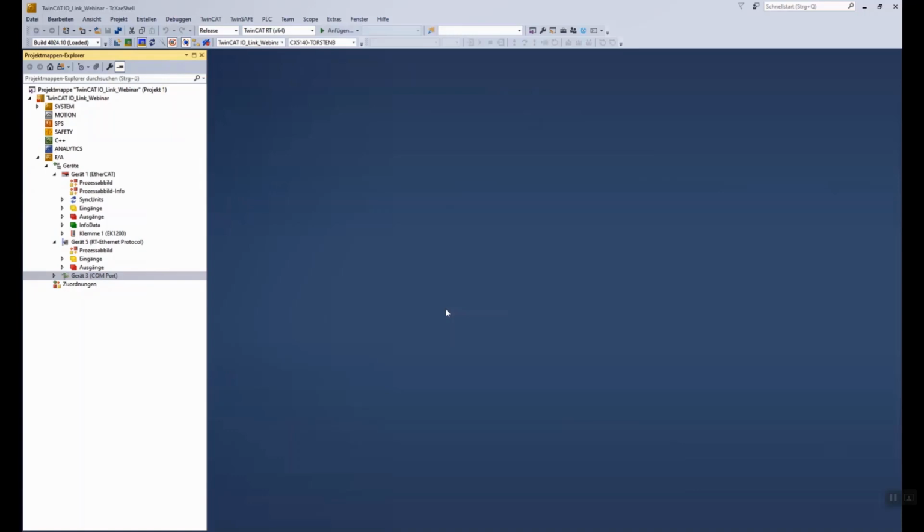IO-Link topology. And if an IODD file is not already on the local PC, then TwinCAT connects automatically to the IODD portal, where I think by now there are around 15,000 different sensors and actuators available with IO-Link. So we're doing a direct connection. You don't have to take a look at every single sensor supplier homepage to download the description file.